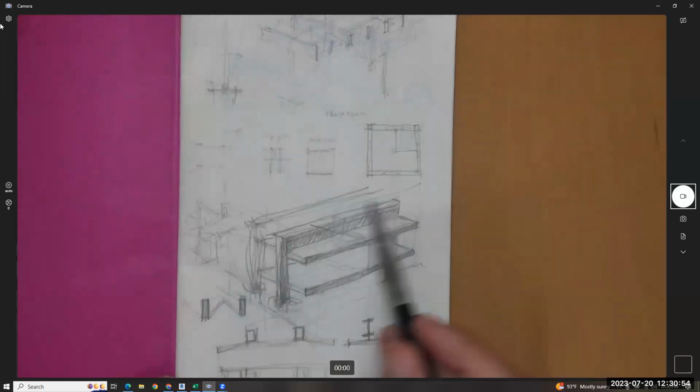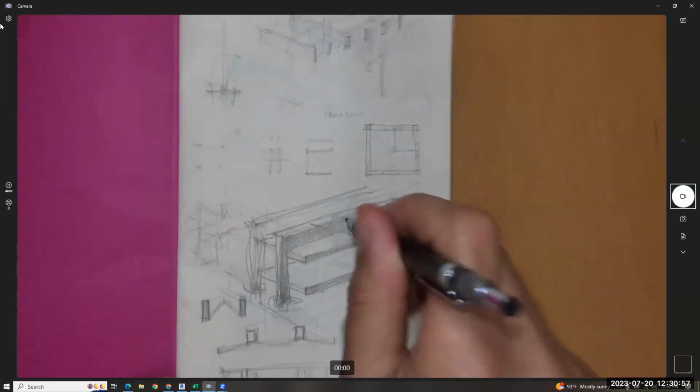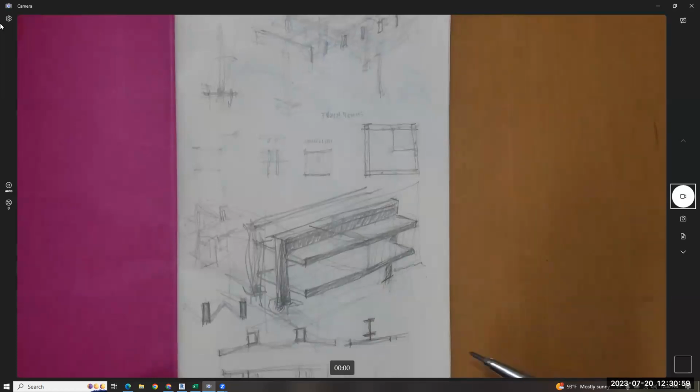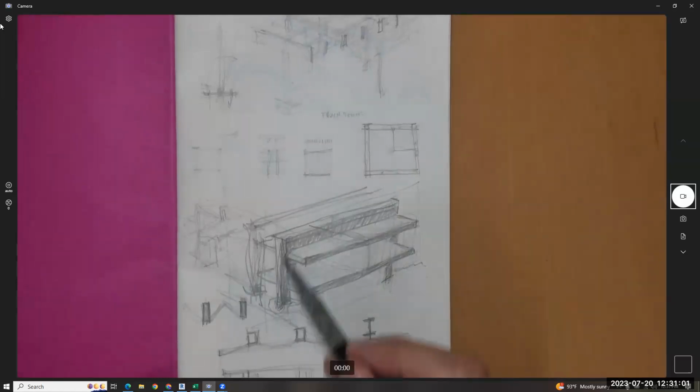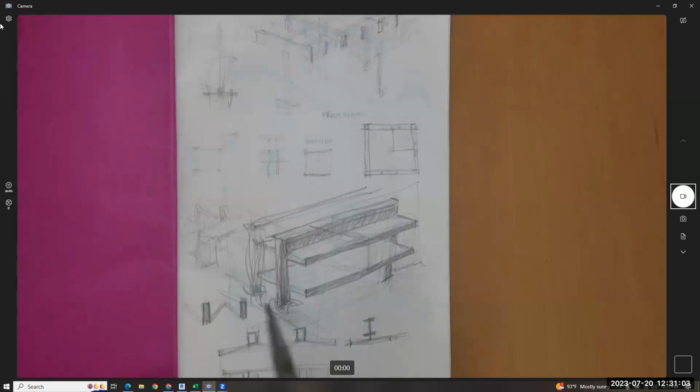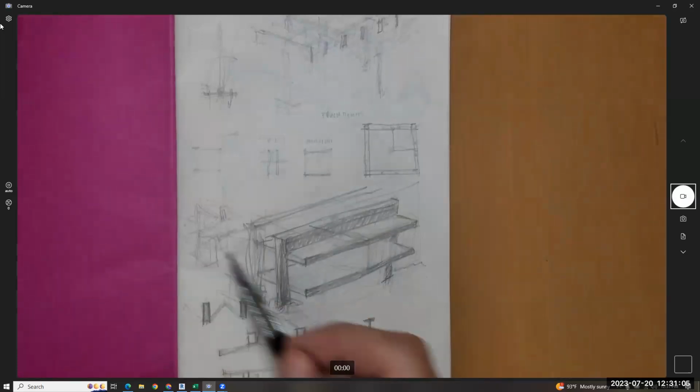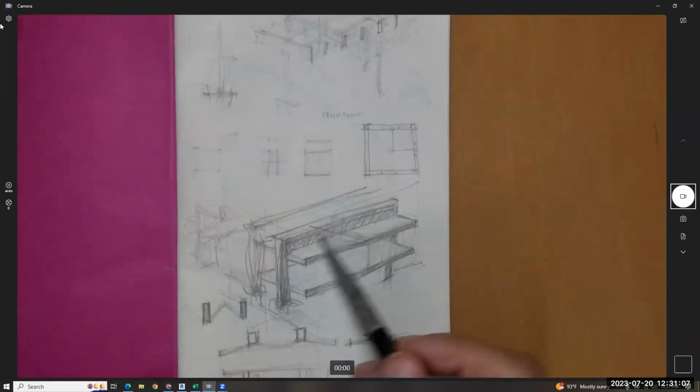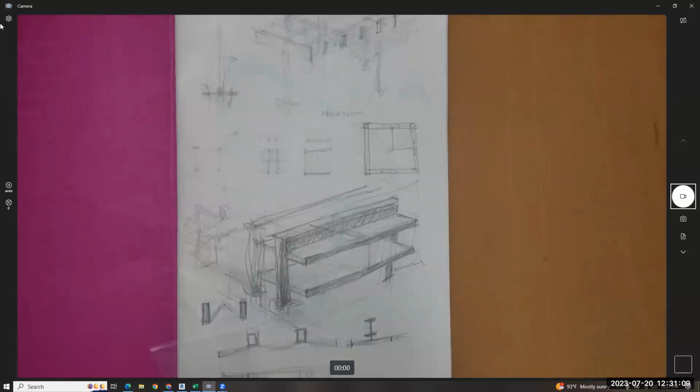Everybody just put in the planes and labeled. I want you to color code the thing that is that thing. Okay, I want you to say, this is the moment frame that's resisting this way. This is now in the Z plane, we've got concrete slabs on the floors that are starting to get us the lateral. So it's a shear diaphragm, just kind of standard.